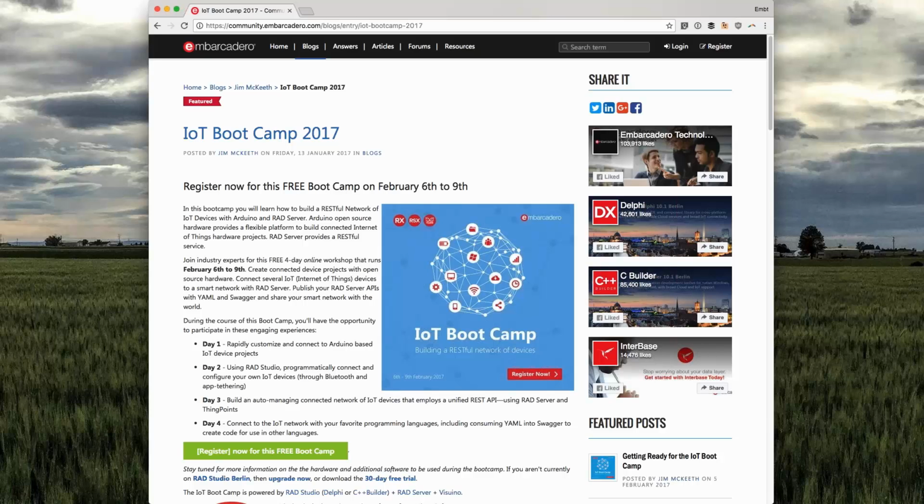Also, with Visuino, it's quite easy to hook multiple boards to work together with I2C communication, and I have even posted some tutorials on that. So you can create, for example, a master I2C board controlling a number of other Arduinos as slaves, and yeah, you can create quite complex solutions with it.